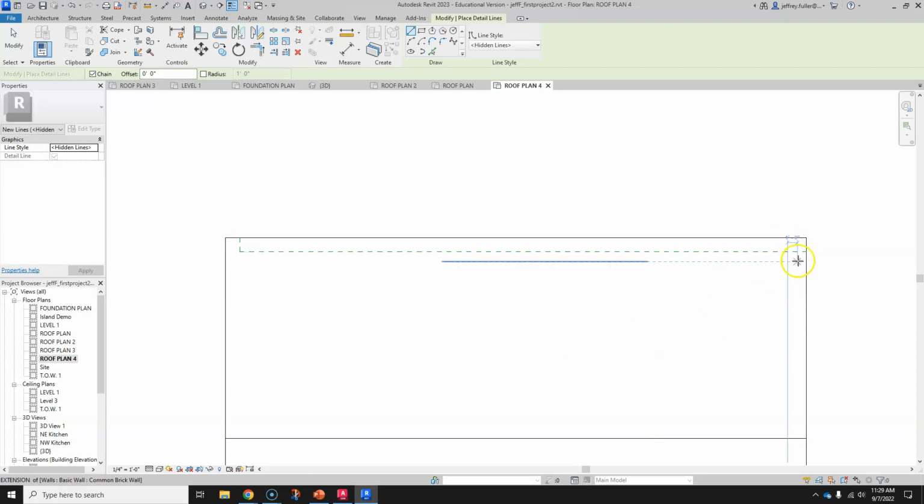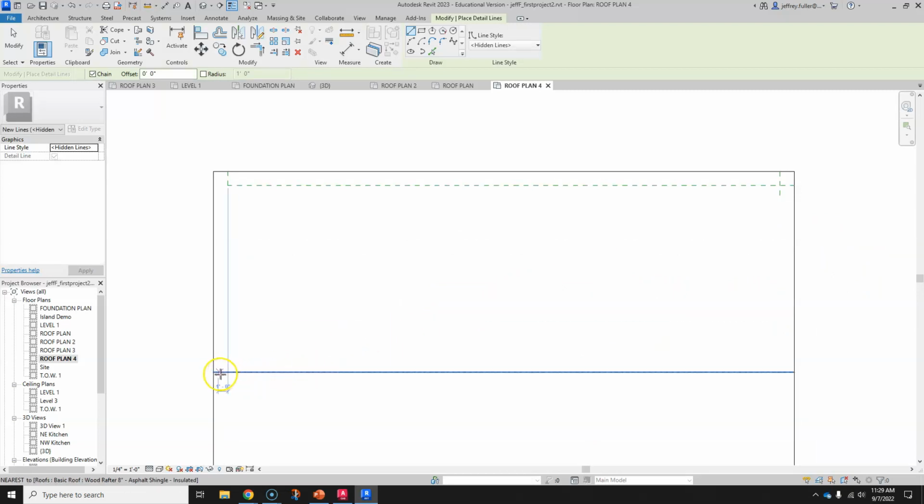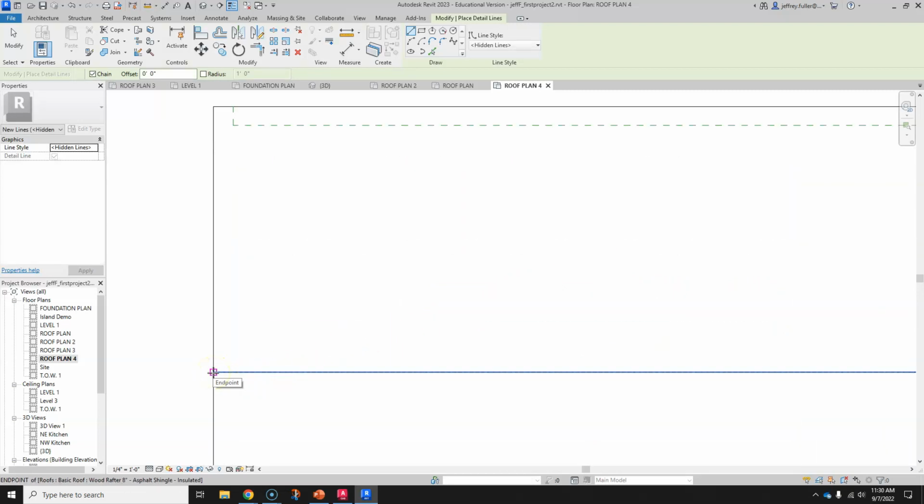And I might even want to reference this other wall as well, so I'll know where that's at. Okay. Next one I'm going to do is come 3 feet from this line, from the ridge line. Okay, and I'm going to have to see what it's measuring here. I'm actually going to come inside a little bit, because my temporary dimensions aren't identifying the areas that I want identified.